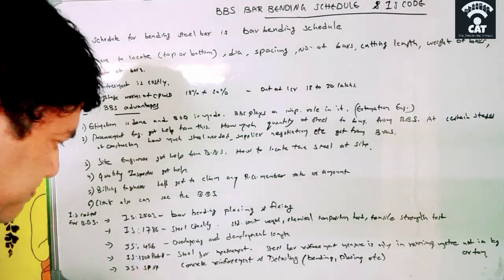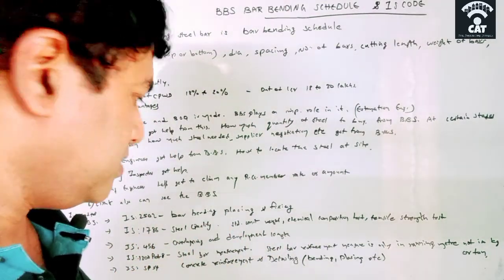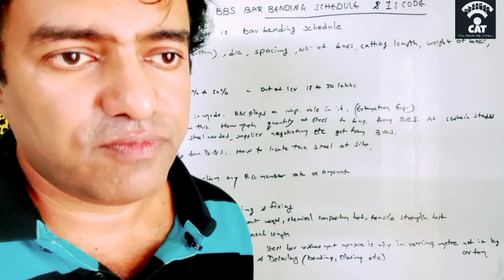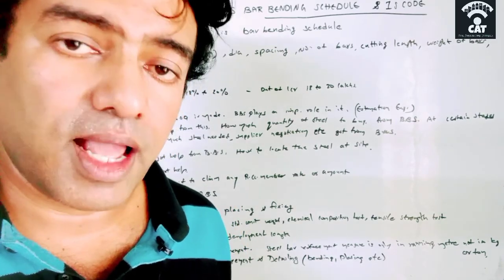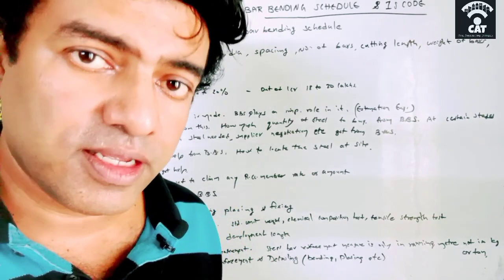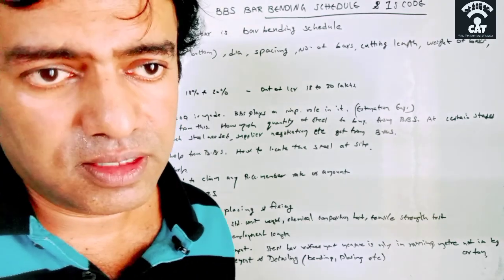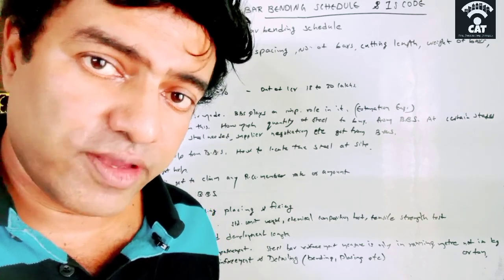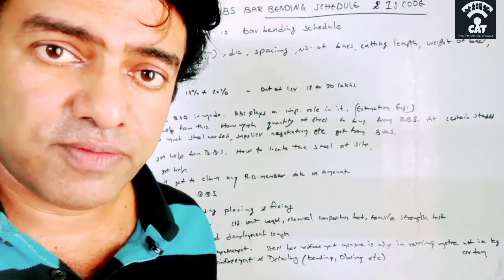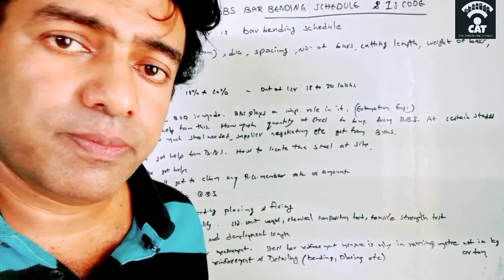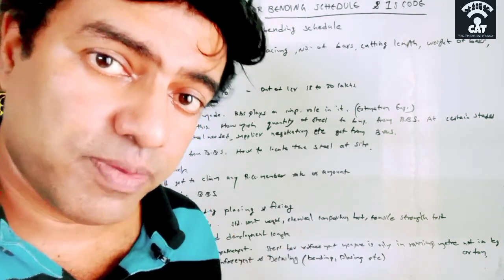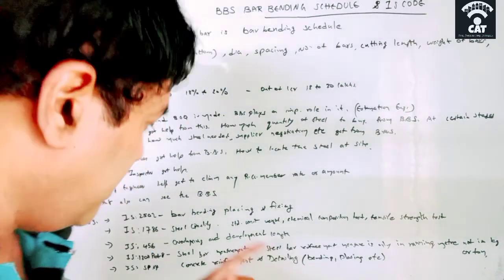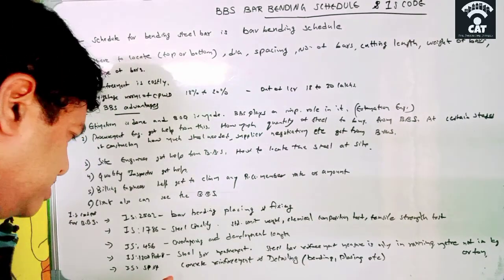And the fourth one is IS 1200 Part 8, which deals with steel bar measurement. As we know, steel is measured in weight in all construction, but actually the IS code says that steel should be measured in terms of running meter only. This is a main important point which most engineers face in interviews. So this is a very important thing that you should remember, that steel must be measured in running meter, as per IS code 1200 Part 8. So please remember that. And the last one is IS SP 34.